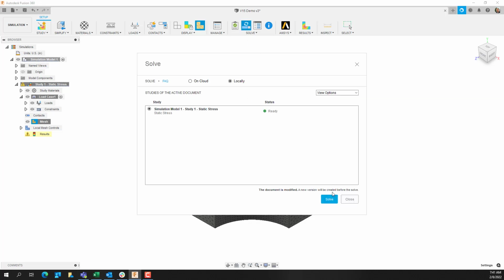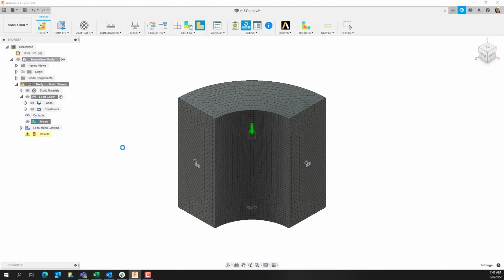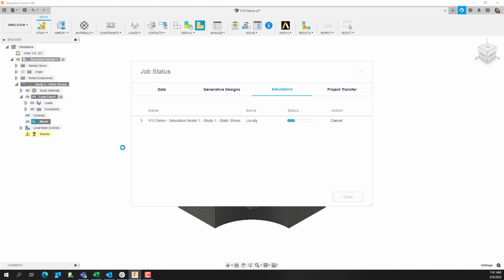And it's probably actually a good idea to run several different mesh sizes, right? You notice between those two, I didn't improve the results of my model anymore, but those results were very similar to what we had in the first run. So that gives us a little bit of additional confidence in the results that we're getting out of the model.